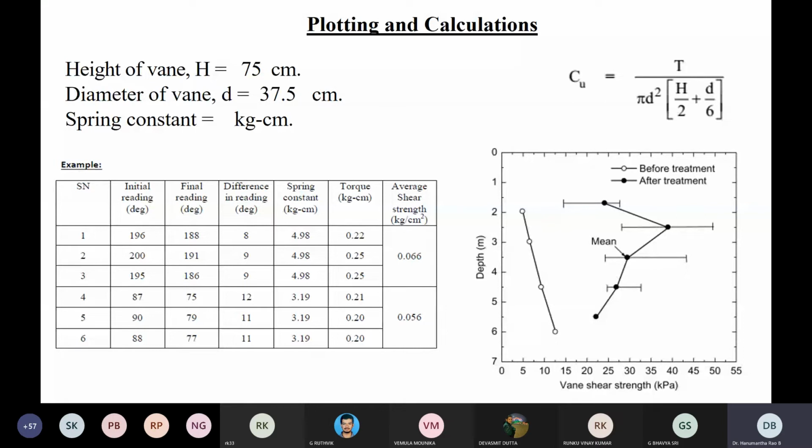They hold the water literally because of the electrochemical forces, or what you have been told is the diffused double layer. So when clay particles hold the water, they form a diffused double layer. So just imagine when there is a diffused double layer, and you are conducting the strength test, what happens? This diffused double layer will act as a slippery. That's why all clay soils are highly slippery. This slipperiness is not because of the clay particles. This slippery is slippage between the water molecules.